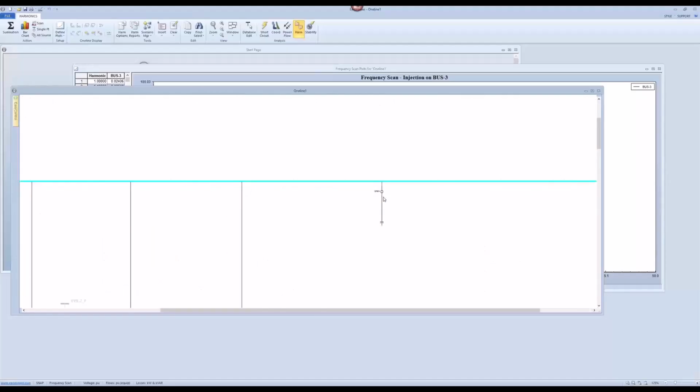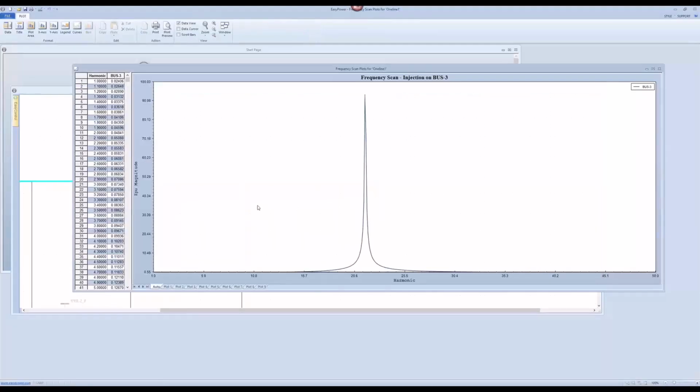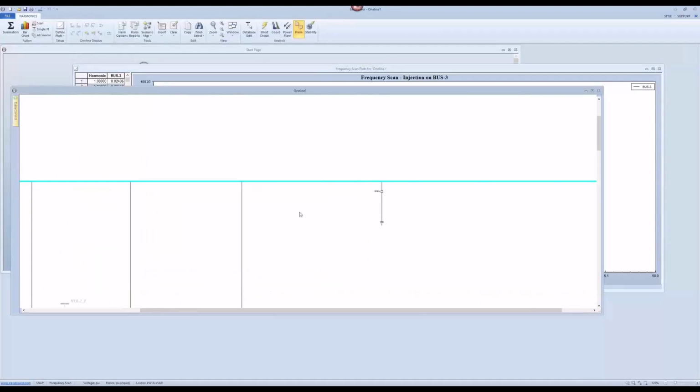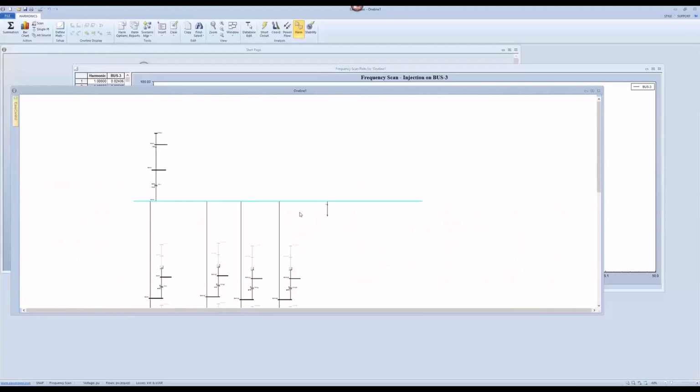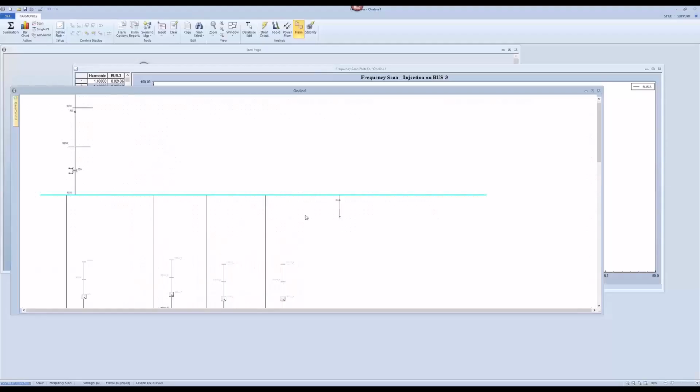So it's possible that you will have a higher voltage and eventually have a higher current demand distortion at the 5th order, 6th order, and 7th order. I mean, it depends on how large the compensation is, right? You can see that the larger capacity you put over there, the closer you are to the fundamental, right? So this is what we have learned in our past studies as well, and this is the message we want to broadcast. In fact, it's an industrial practice not to install too many capacitors at the 34.5.